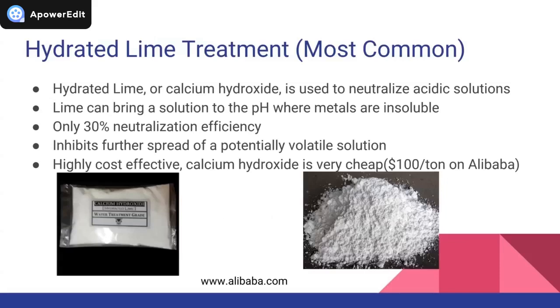Okay, so just to introduce the most basic aspect of the solutions, any treatment of acid mine drainage involves chemical neutralization of the acidity, followed by the precipitation of iron and other suspended solids. Most cases of AMD are treated with an alkaline addition, so basically just increasing the pH of any drainage solution. Both hydrated lime and caustic soda treatments are considered active solutions because they involve adding alkaline material at the source of the drainage.